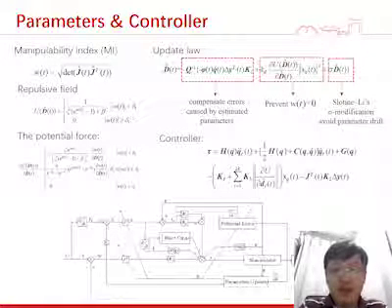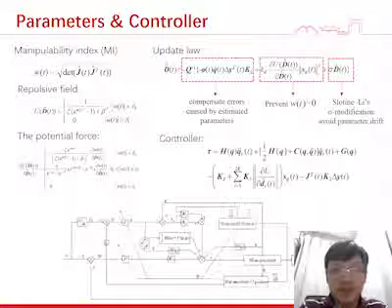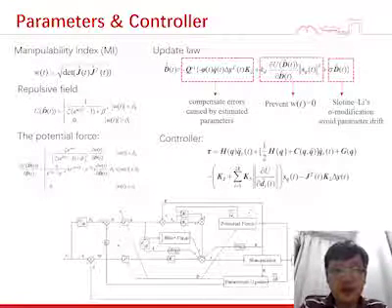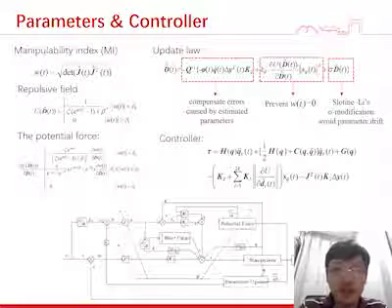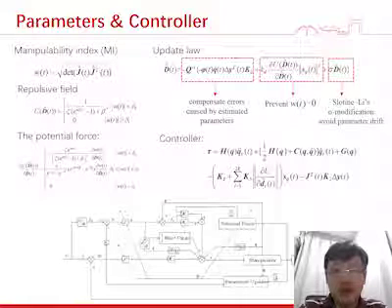As for the controller design, the block diagram of the proposed controller system is shown in this figure. The adaptive algorithm for the online estimation of D is as follows. The first term compensates for the error in the closed-loop system caused by the estimated parameters. The second term is to improve the maneuverability of the system, which is realized by introducing a virtual force that drives the estimated parameters away from the value resulting in Wt equal to 0. The last term is used to avoid parameter drift, referencing the classic Slotine-Li modification method.